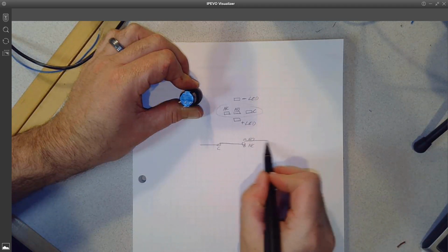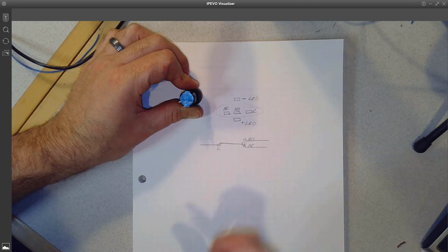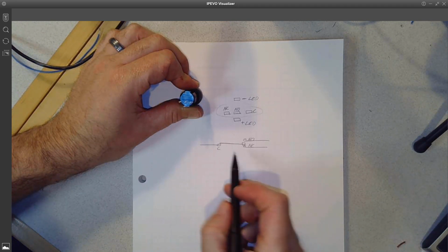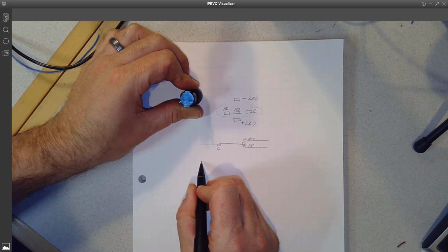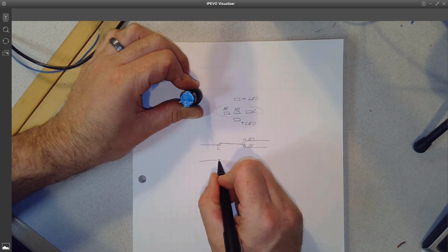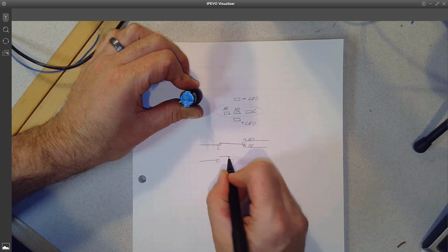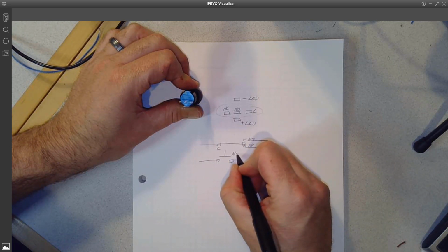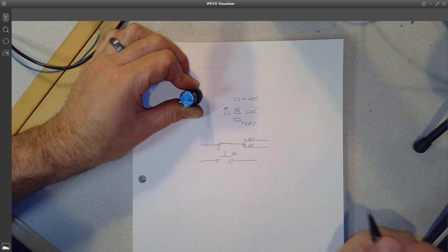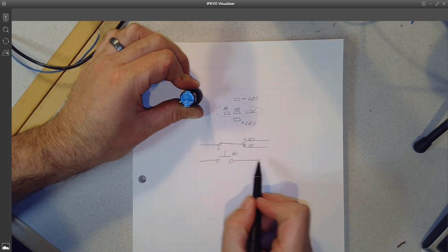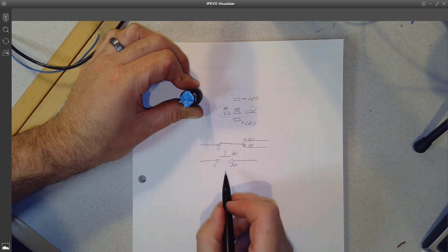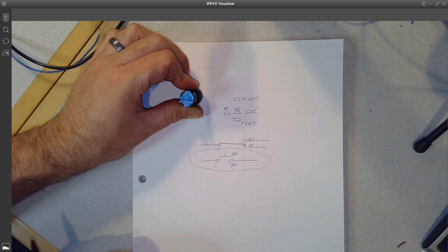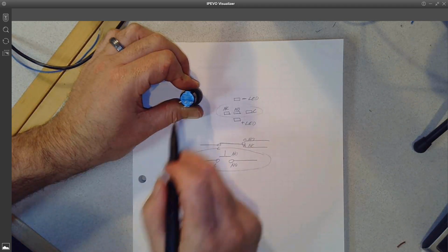And then we can connect the normally open onto other devices and our normally closed. So when you're drawing a schematic, if you needed to draw the whole thing, you could draw it like that. But since we're just using it as a push button, we'll use the push button format, which is more like that. And we're just going to use the normally open of the push button style for right now. So you can use that. This would be your common terminal, and this would be your normally open terminal.